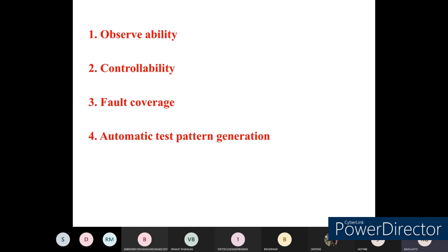And there is one more method, which we call delay fault testing. In delay fault testing, because of the parasitic generation of the metal wire interconnects, failures will occur in the VLSI CMOS system that will reduce the performance of the functionality of some of the subsystems, and it will also affect the timing constraints of the device. Such a timing analysis we call delay fault testing.